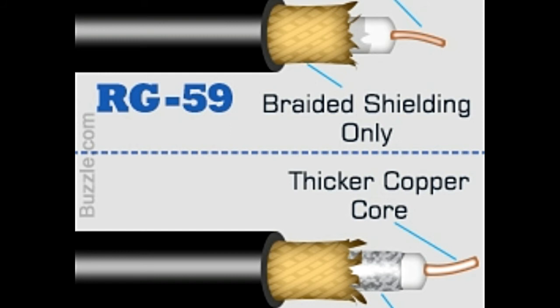Operating frequencies. RG59 is made for appliances that require signals of frequencies lower than 50 MHz, such as high-definition plasma televisions or video projectors. However, this cable is unable to cope with signal frequencies which run in gigahertz, because the wiring and shielding is too thin. Therefore, the quality of the signal is lowered, and it cannot be used for satellite and cable transmissions.